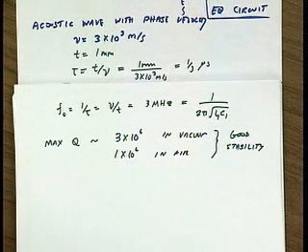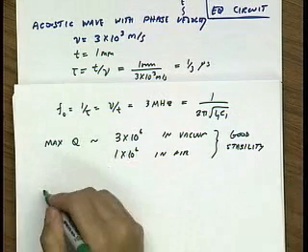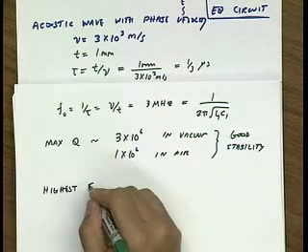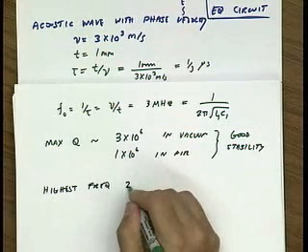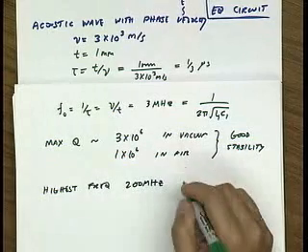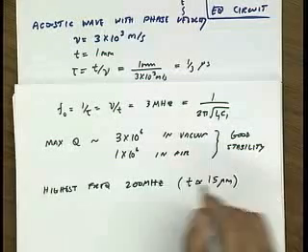Now, one of the problems with the quartz technology is a frequency limitation, because the highest frequency you can go depends on the thickness of the material. Commercially you can buy up to about 200 megahertz crystals, which corresponds to a thickness of only 15 microns.